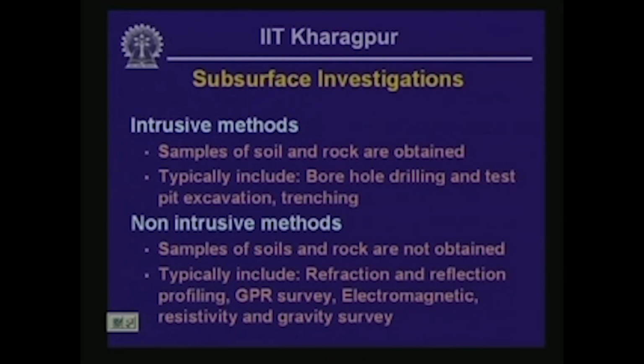Alternatively, subsurface investigations could also include non-intrusive methods in which no borehole is excavated or drilled or a test pit is excavated through the geologic units. In these testing procedures samples of soils and rocks are not obtained, and typically these procedures include refraction and reflection survey. We are going to talk about these different procedures again in greater detail later on in this course.